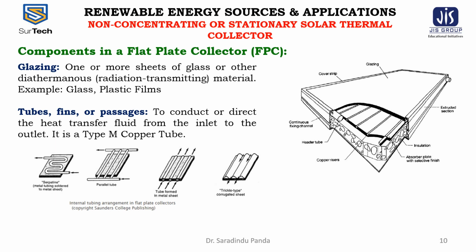The flat plate collectors can involve the liquid or the air heat transport. Water is one of the common options as the liquid fluid due to its accessibility and the good thermal properties. It has the relatively high volumetric heat capacity, and it is incompressible or almost incompressible. It has a high mass density also.